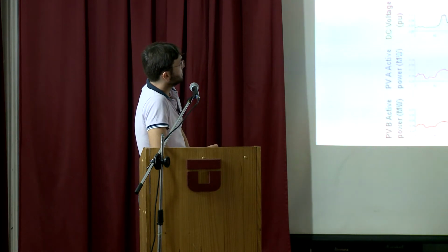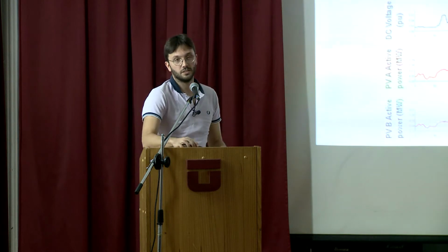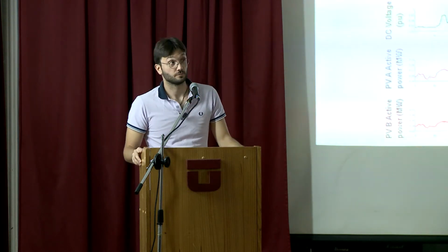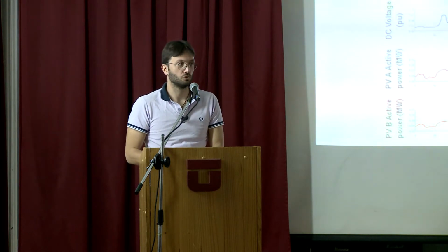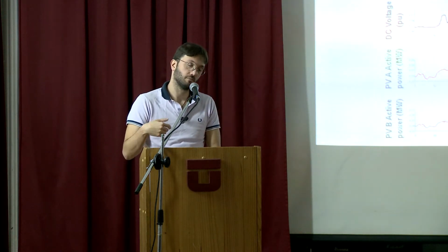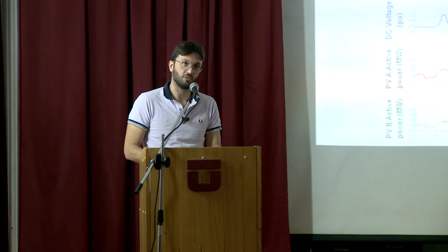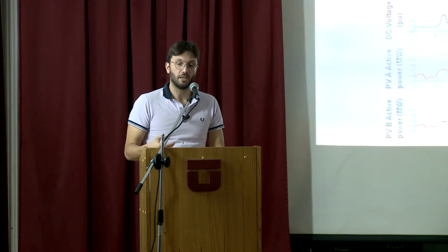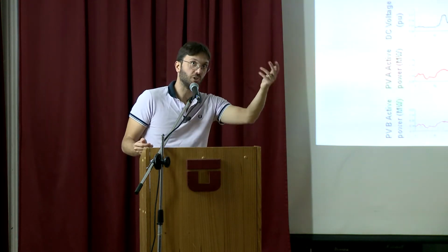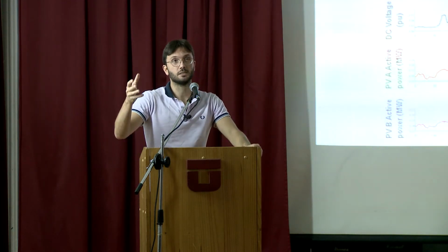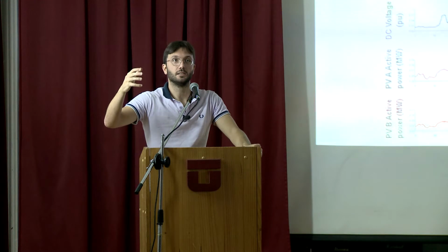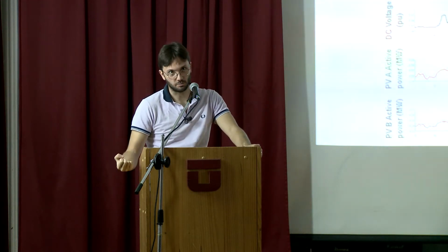If the bandwidth is a bit lower, then we are in this bouncing behavior where the system is too slow. Too slow means that I see that the DC link goes up, I increase the frequency. The PLL is slow to react, I keep increasing the frequency because the DC link voltage is still going up. Then at some point, the PLL detects the frequency and starts reducing the power.